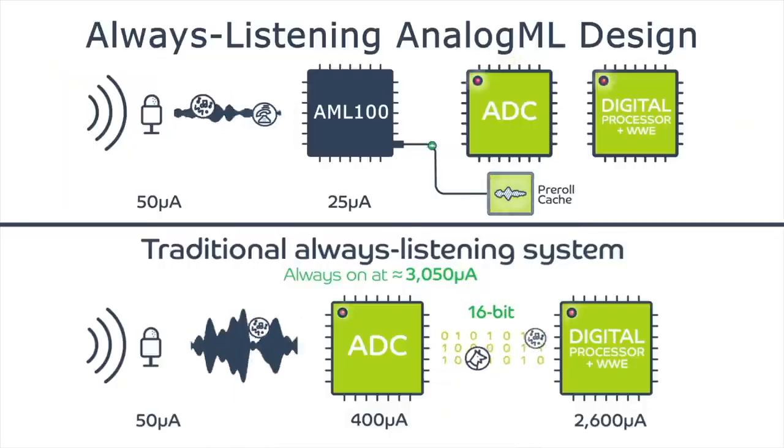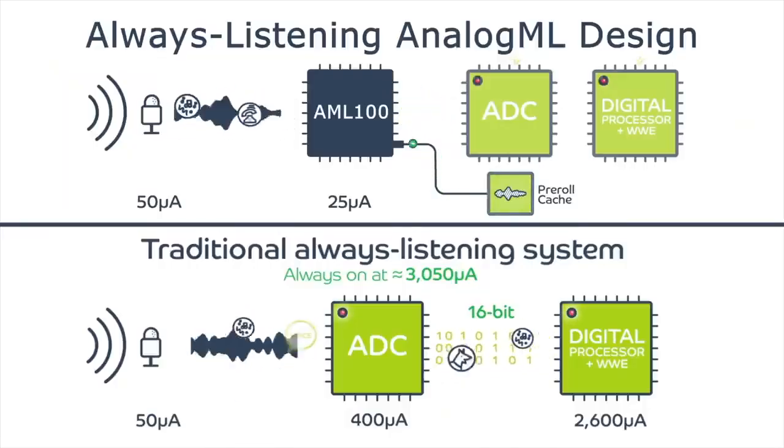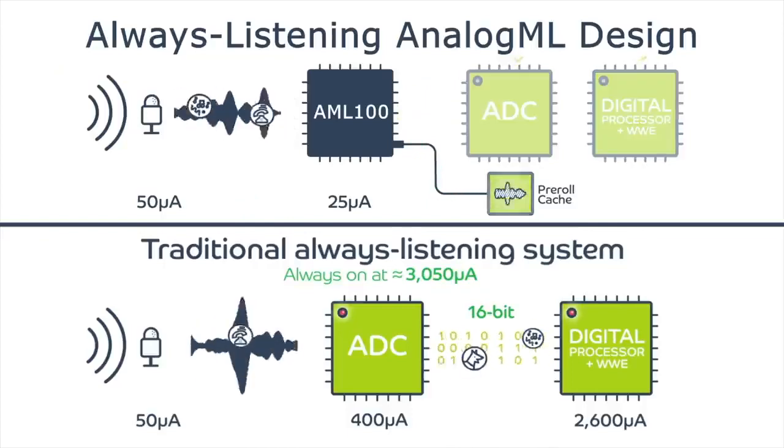Some have proposed using analog circuitry in smart home speakers solely to listen for the wake word, like Alexa or Siri. They would use a lot less power and be able to quickly and reliably turn on the digital circuitry of the device. But you still have to deal with the challenges of analog. For one of the popular networks, there would be 50 sequences of matrix multiplies that you're doing. Now, if you did that entirely in the analog domain, by the time it gets to the output, it's just so distorted that you don't have any result at all. So you convert it from the analog domain back to the digital domain, send it to the next processing block, and then you convert it into the analog domain again. And that allows you to preserve the signal.